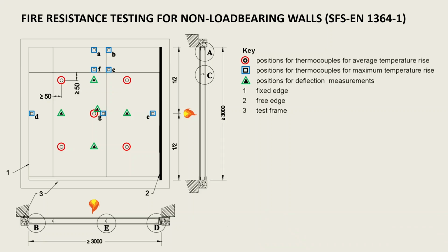Here are some conditions to note about the test. All specimens should measure at least 2.8 to 3 meters unless naturally smaller. Only full panels or boards are used. That way we minimize cuts. Vertical or horizontal joints are included in the test if they exist in real-life use. One vertical edge is kept unrestrained. Failures within 150 mm of the edge are excluded. And finally, standard support conditions are followed wherever possible.